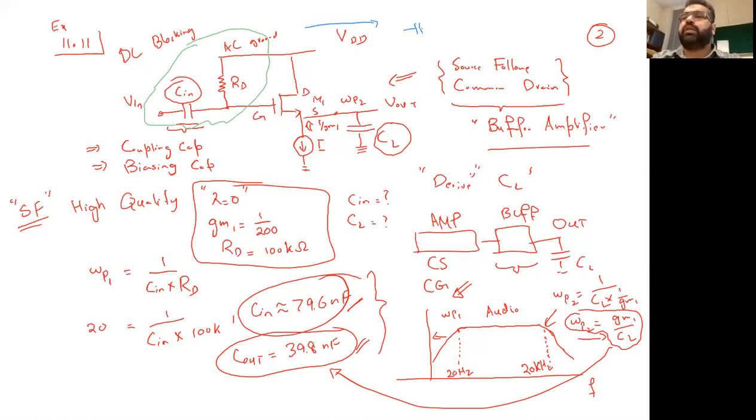C in, and I'm taking my output at RD. So here I'm taking my output and this is my C in. This is the node, if you want to call it Vx, and this is the same thing we saw in the last slide. This is your V in. If I take the output across a resistor, I have high pass characteristics as compared to low pass. And in general, we call this the mid-band gain.